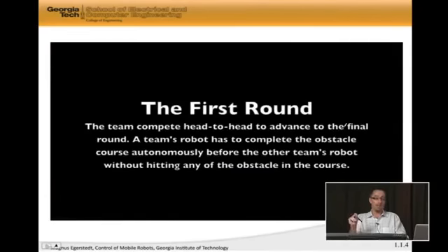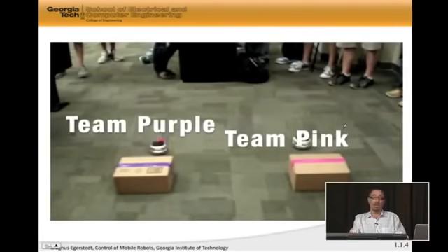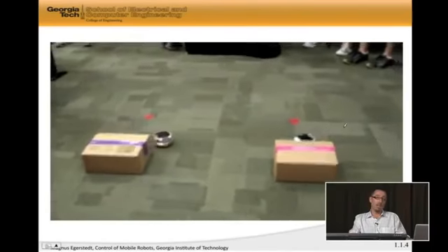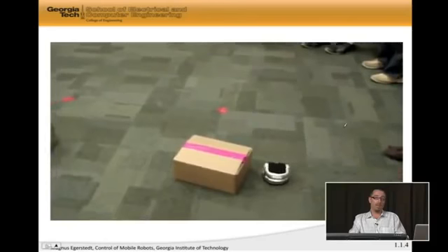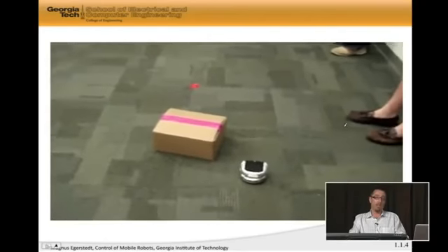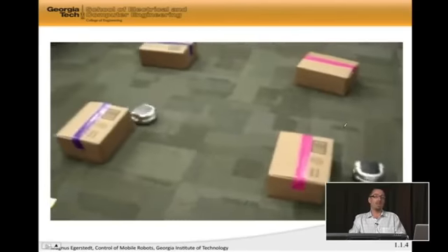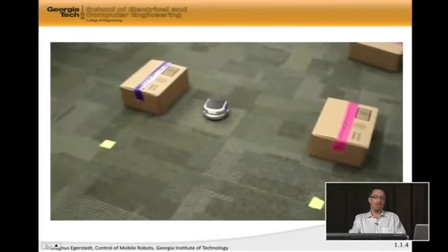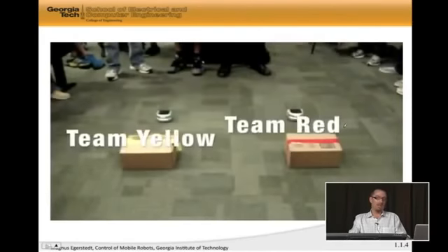And we had students actually compete, not at the AI level or the perception level, but purely on the controls level, to achieve certain tasks. So here you see, for instance, one robot that's a little too aggressive. It's also oscillating, so there's something not perfect with this control design. It's also a little slow. The robot over on the left oscillates less, but it's a little bit slower.